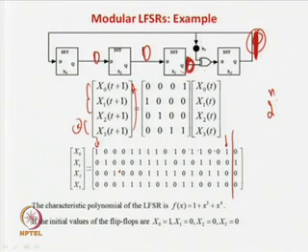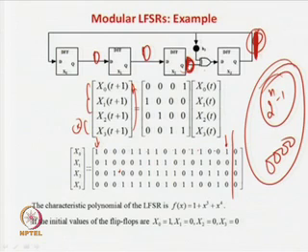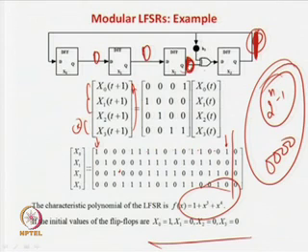So, 2 to the power n minus 1, if you are excluding the all 0. So, an exhaustive test pattern has been generated by using this characteristic polynomial. In this case, if you have an application where you have to generate 4-bit vectors for your testing, and you assume that these 3 are your more important test patterns, and then this one.